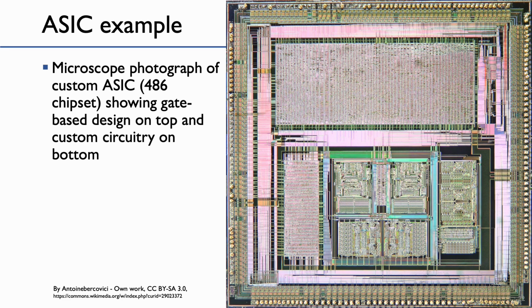So basically there'll be logic gates and flip-flops, and they'll all have the same physical height, and it looks on this diagram that they've all been laid on their side, and that will get automatically laid out and wired up. And you can see on the bottom part of this photograph that there are some very regular structures, and those will have been laid out either by hand or using scripts that lay out these geometric patterns.